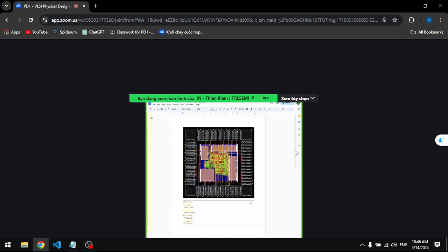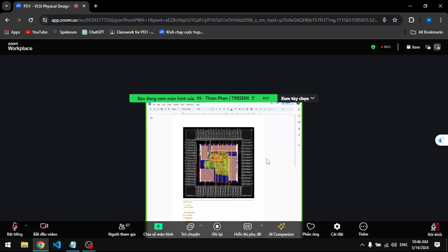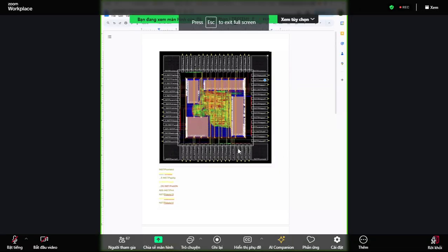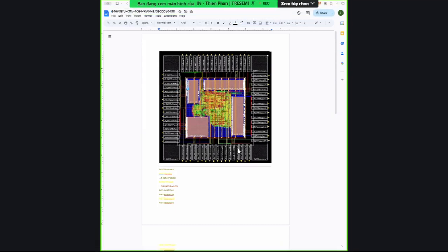Yes. So essentially this is the picture that Vũ Quang Minh uploaded to his Google account. I noticed that he has a lot of dangling wires here. It's not too detailed, but I'm guessing there's a gap between the memories. So when you create the rows, you don't want a tiny, very short row where no power can be connected to that M1. So those M1s are essentially floating.